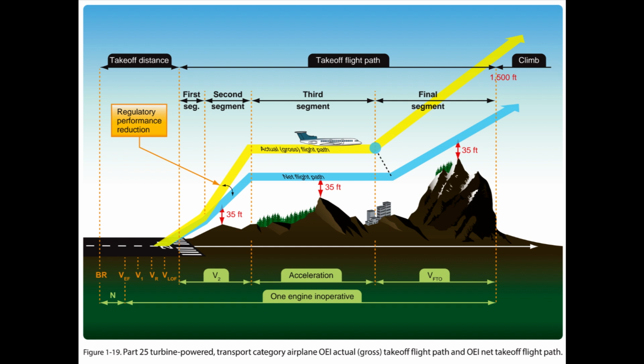The OEI-net takeoff flight path obstacle clearance assessment must also account for clearance of the low, close-in obstacles that are noted on the IFR departure procedure, but are not necessarily cleared when complying with the TERPS-based IFR climb gradient. The OEI-net takeoff flight path is unique for each aircraft type and is assessed on each takeoff for the required obstacle clearance directly against those obstacles located beneath the OEI flight track and within the prescribed lateral distance from the flight path centerline. TERPS, on the other hand, provides a required climb gradient that represents a surface that the aircraft's all engines operating climb profile must remain above throughout the IFR climb until reaching the en route environment.